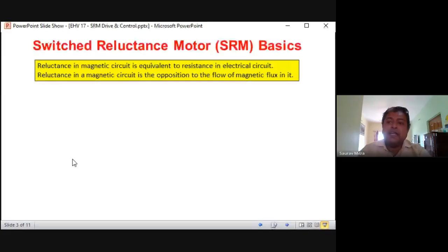So that's why we find that whenever the flux lines enter the air, they just blow out. If it is flowing through a single channel, say there is a metal path here, then through that metal path all the flux lines are flowing for the magnet. Then suddenly between the north pole and the south pole there is a gap. Here is the north pole, here is the south pole, and it is a horseshoe kind of magnet. In the horseshoe magnet, all the flux lines are contained within the magnet, because it is the least reluctance path, so all the flux lines are concentrated within the magnet, but between the north pole and the south pole there is an air gap in between.